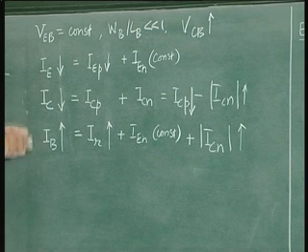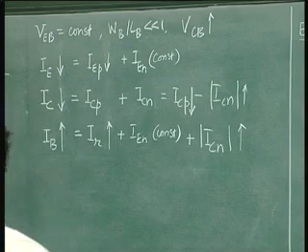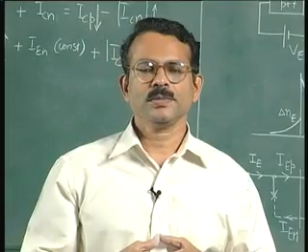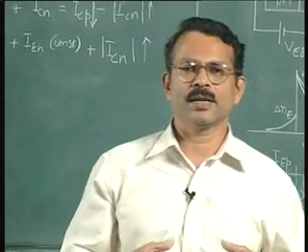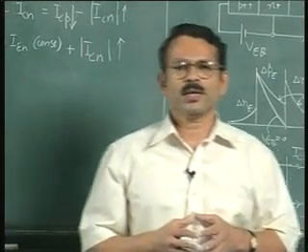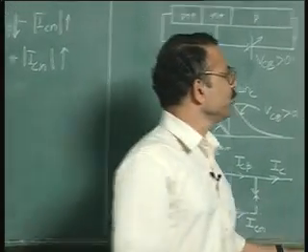So this is really undesirable. Each of these things is undesirable. So the transistor action is destroyed if you have forward bias across the collector base junction. So this is not desirable. Now let us see whether a reverse bias is acceptable. What happens if you have reverse bias?